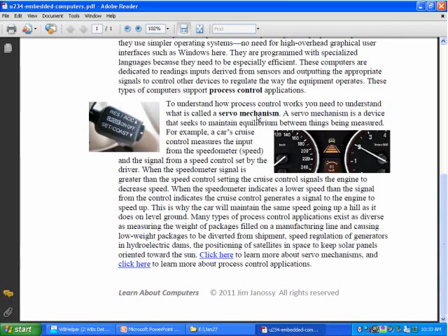The computer, the little embedded computer, reads that and is also reading the speed of the car. And it compares these two values, which have been digitized so that it can do this with a little digital program. And if the car is moving slower than the signal, that is, the speed indication is lower than the setting that's desired, the computer gives the engine the signal to speed up. And it keeps measuring things, and finally the engine speeds up enough that it might even be pushing the car faster than the setting, and so then it cuts back and it tells the engine to go a little bit slower. So this thing, one machine, namely the computer, is controlling another machine based on sensing what's happening with that machine.